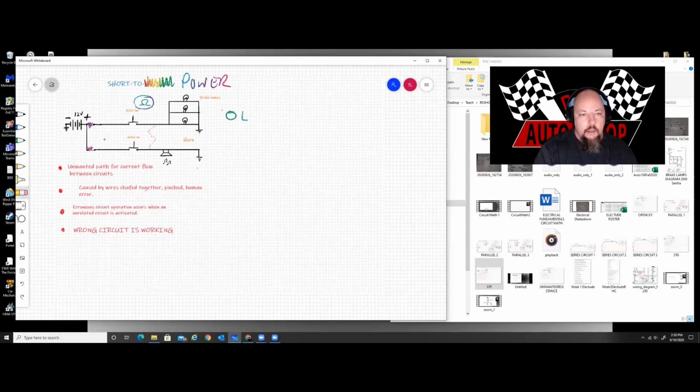Okay. Now what I'm going to come on over here and do is connect, oops, I'm not going to erase my work is what I'm going to do. I'm going to connect one meter lead here to this side of the switch terminal, and then connect one over here, and then all of a sudden, I should get some kind of reading. Maybe it says 0.2 ohms or 0.33 ohms or something like that, however potent the connection is. It's enough to travel current between the two circuits.